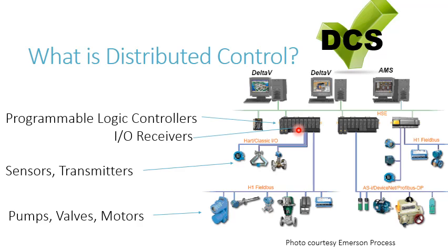The signals can be analog or digital. That's quite important. We'll go into all these details. The PLC does the logic to do the control, and it sends the control instructions back to the actuators to actually do the control. And finally, we've got the highest level here, which most people think of when they think of distributed control systems. You've got the high-level control center monitoring, the data analysis, the data collection, and we're going to go into that.